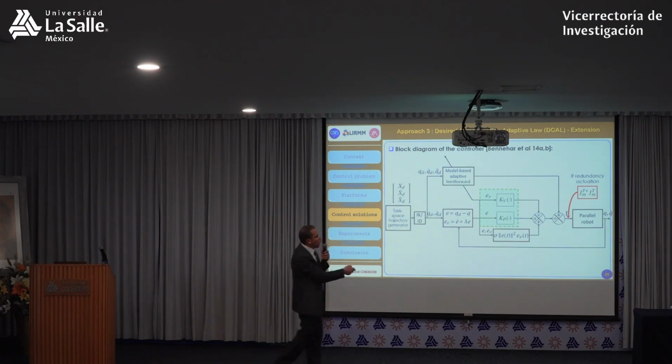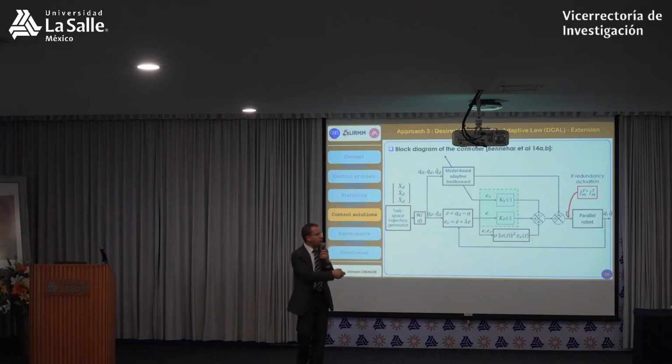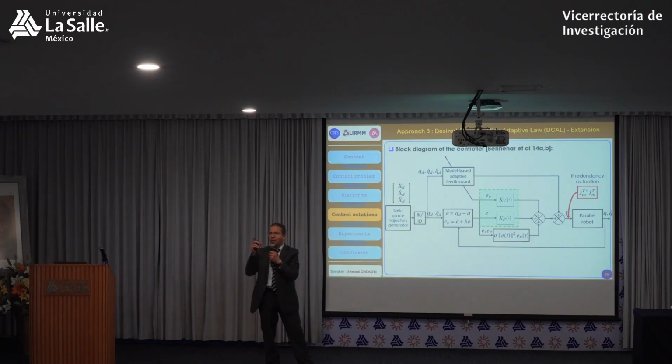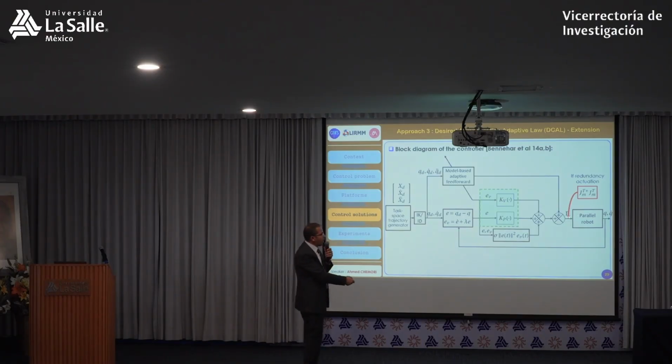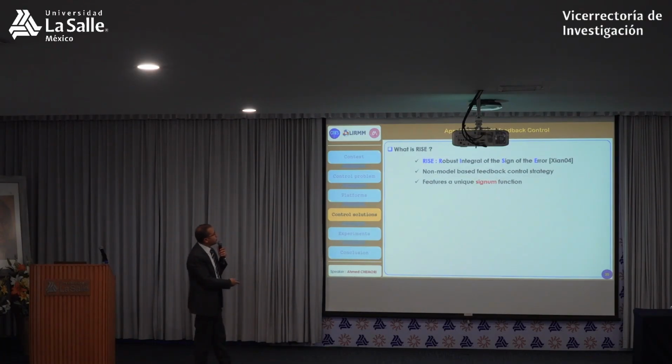You understand why and how we computed this Jacobian matrix transpose multiplied, pseudo-inverse multiplied by the Jacobian transpose. You obtain this term that reduces the internal effort that may appear due to this redundancy in the actuation. So this is the third controller.